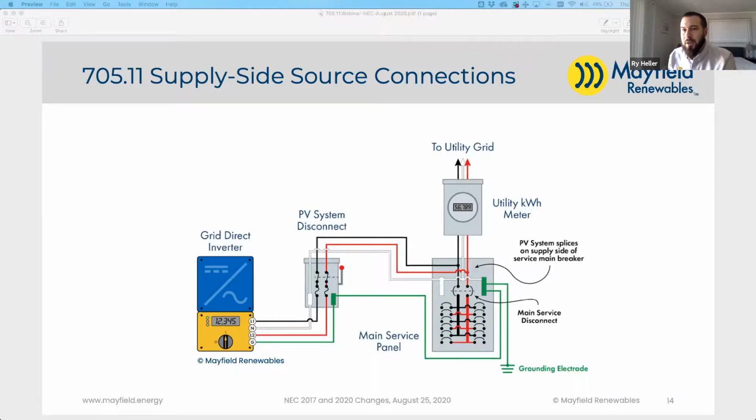I definitely got into this in the article about SolarEdge because it's kind of a factor with those commercial systems. The optimizer I was using was 18 amps. So if you have 3 strings, then 2 strings could backfeed one, causing 36 amps to be on a wire. And if you're running 10 or 12 gauge wire, that would be a problem without overcurrent protection.